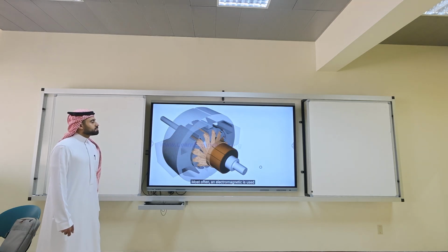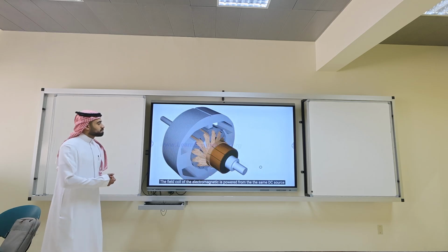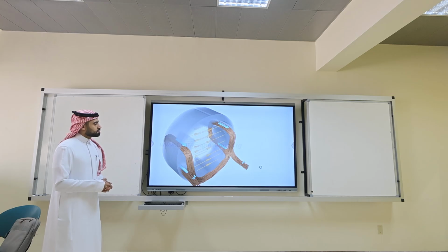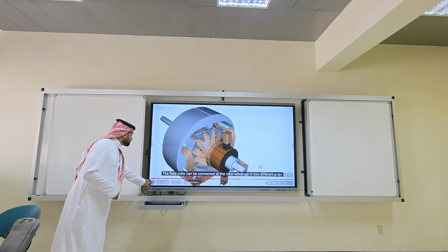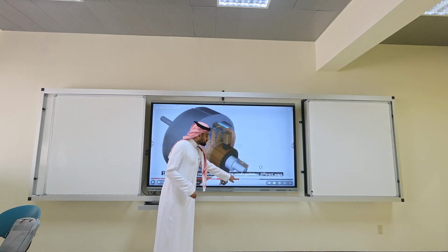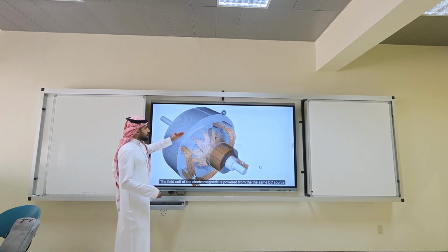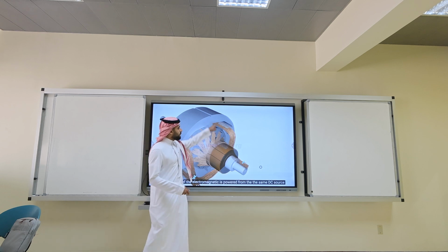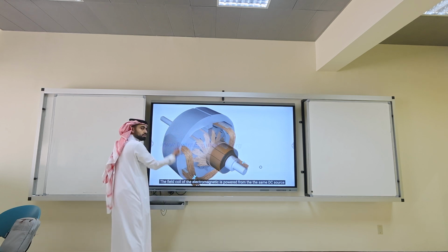Most often, an electromagnet is used. The field coil of the electromagnet is powered from the same DC source. Okay. Now, the field coils can be connected. What did they do? Instead of the magnet, put what we call the stator, laminated, put a coil here and a coil there, apply the right hand rule.